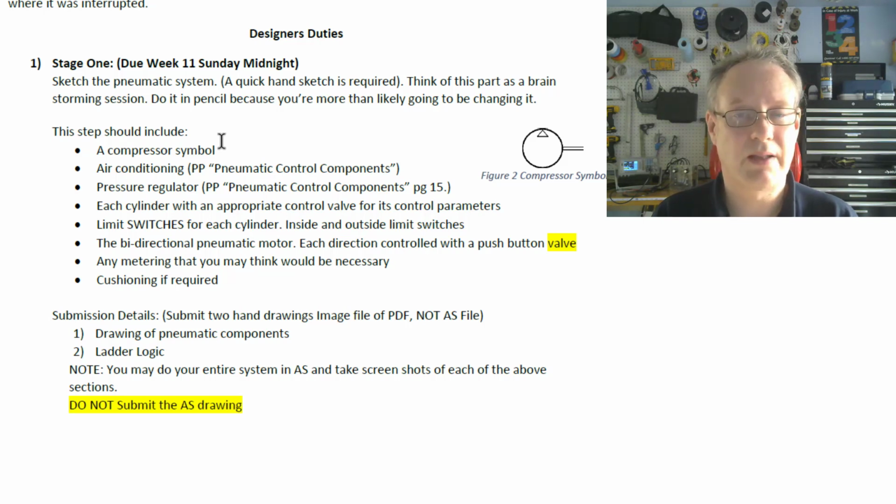You should label the regulator 75 psi. If you want, you can use a system where you put a pressure release valve that's set to maybe 80 or 90 psi, just in case there's a system failure. And if you want, you can also add in some other things. Certainly you have to think about adding safety in.